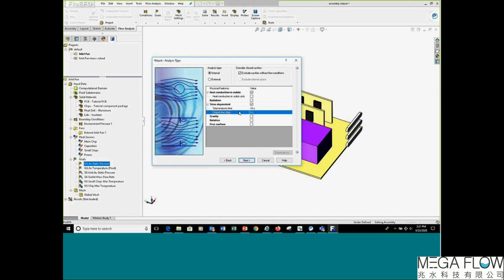The second feature here, the parameter, is output time step. This is the results file. How often do I want a file to be written during that 10 seconds? Every half second, every 1 second? And knowing that I'm running this for a 10-second total time, by defining an output time step here, I know how many files I expect to get. I should get 20 files here, okay?